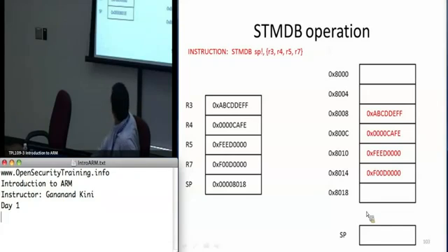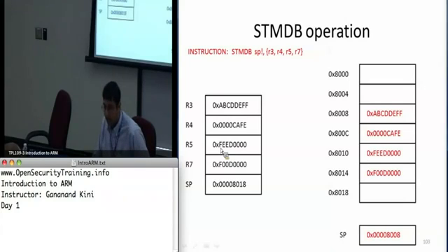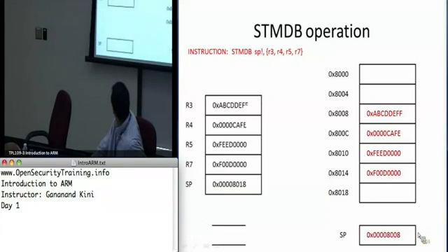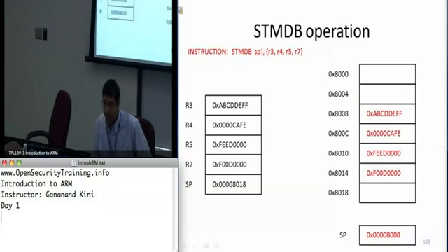Your stack pointer generally points to an empty slot. If you remember from the push and pop operations, the stack pointer points to the top element of the stack, so that's going to be a non-empty space generally. So once you have updated the stack, you want to load it back into the registers, in the epilog. Now the stack pointer gets updated to 8008, which is actually the first element that it started off with.